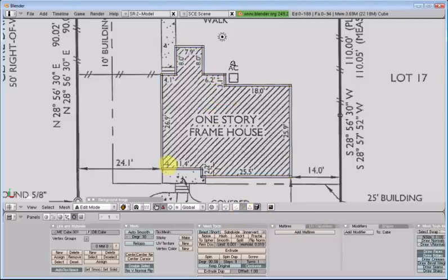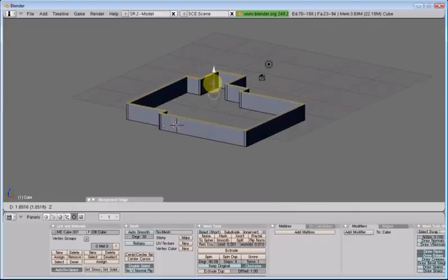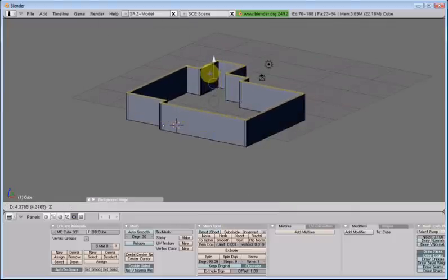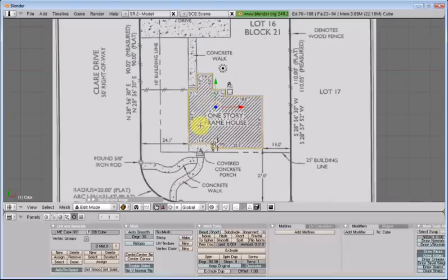And let's ignore background faces, so hit that button right there, hit BB, select everything. And then right click, we'll rotate into that view, and then we'll just drag those edges up. Now we'll measure that out to get it perfect later, but now we've got the basic shape of our house.